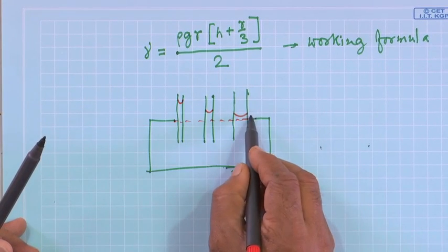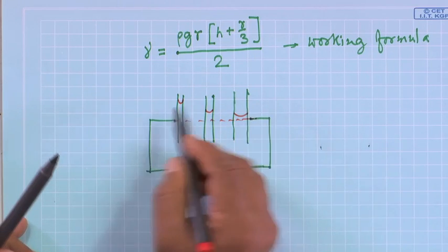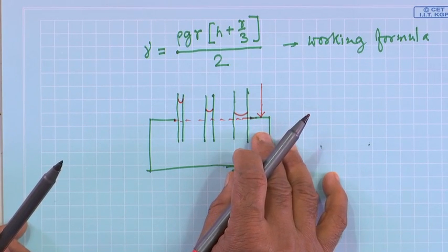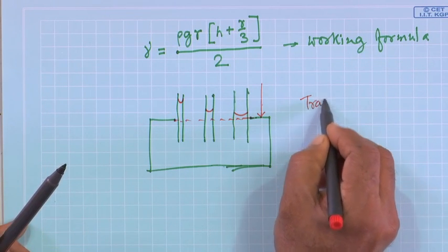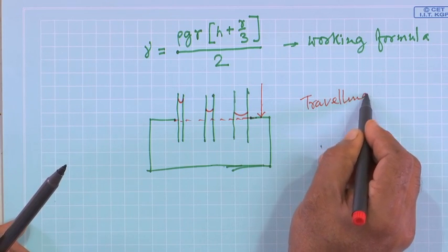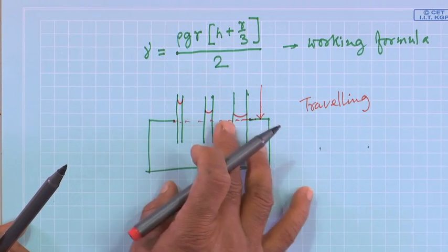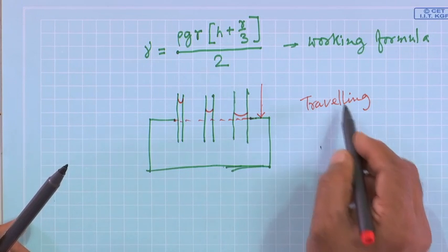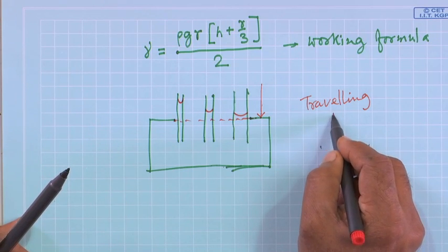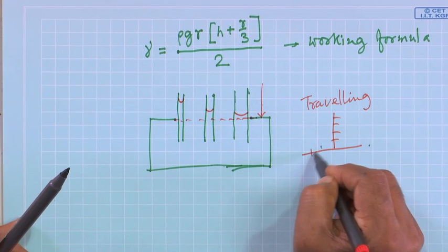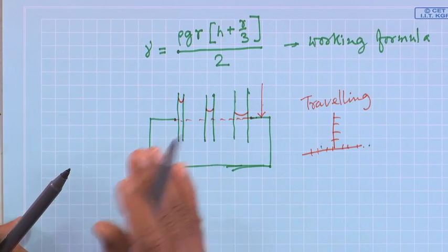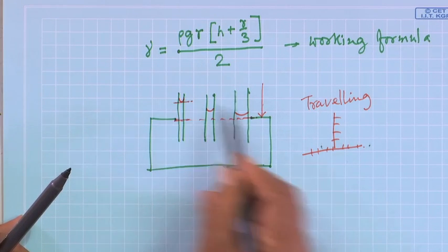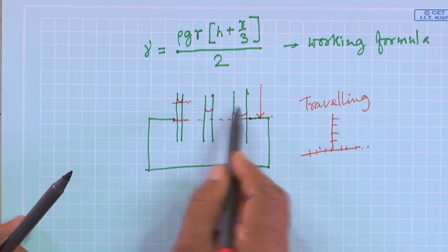Okay. So, now we have to measure the height. So, we will use one indicator, okay. It will touch the surface of the water here in the container, and we will use a travelling microscope, because without a microscope it is difficult to see this and the meniscus. So, the travelling microscope has a vertical scale as well as a horizontal scale. So, in this case first we will set here. Then using the vertical scale we will measure this height, this reading, and we have to take this reading also. The difference of these two will be the H.